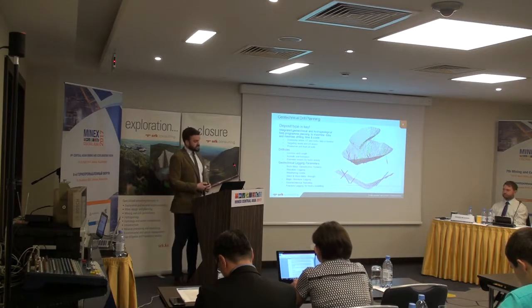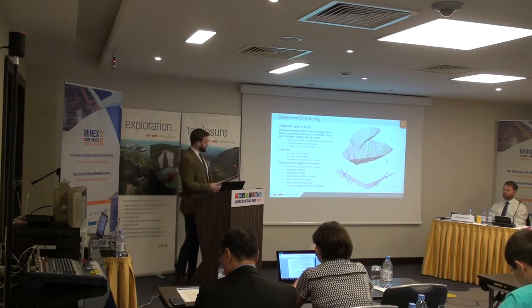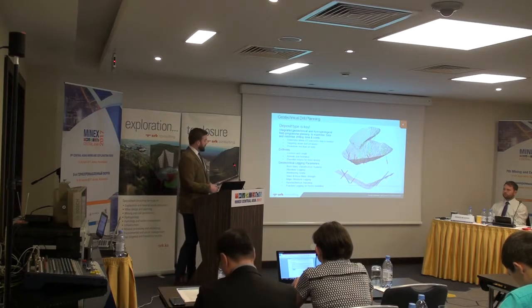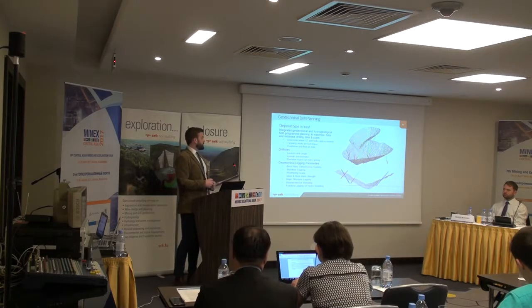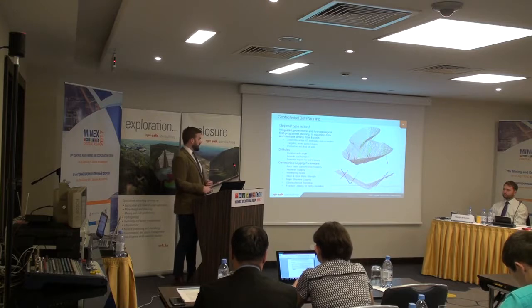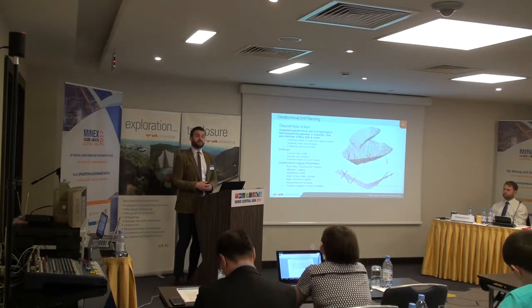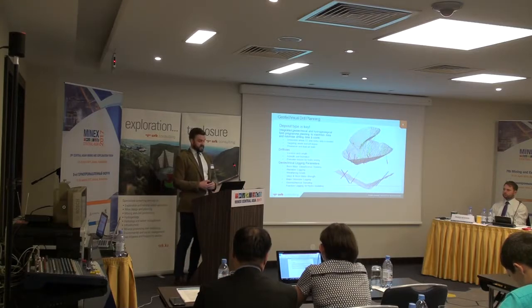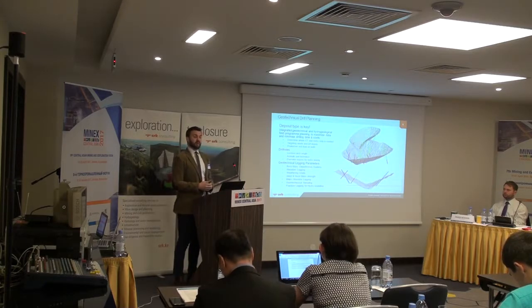And the logging parameters that you should collect, just listed a few here, are your rock mass classification systems like RMR, alteration logging, weathering grade and intensity, rock mass strength, major structure logging. Also, if the holes are going to be used for geomechanical sampling, and also get a good understanding of the fracture logging, because that will have an impact on how the hydrogeological conditions will be affected.